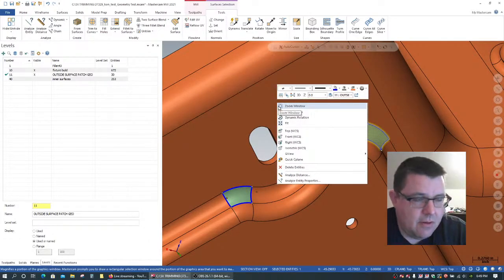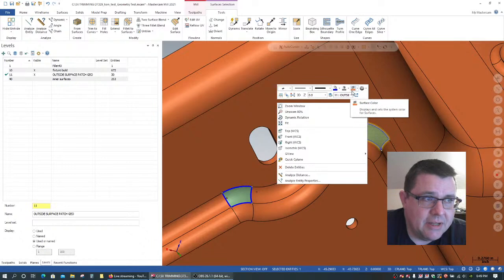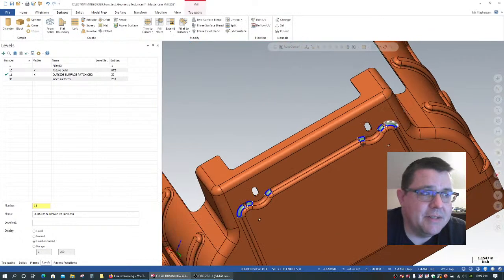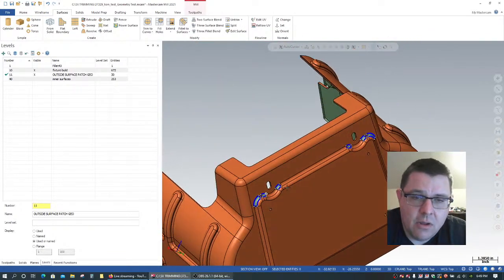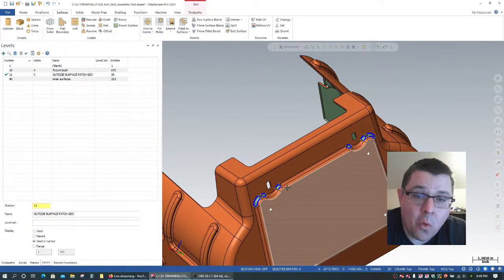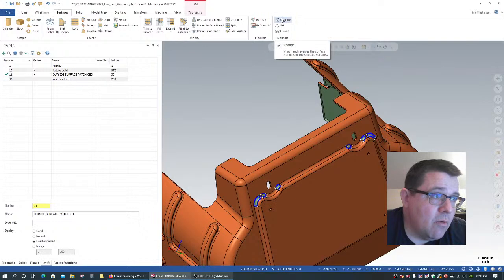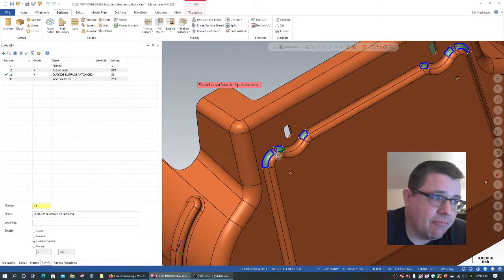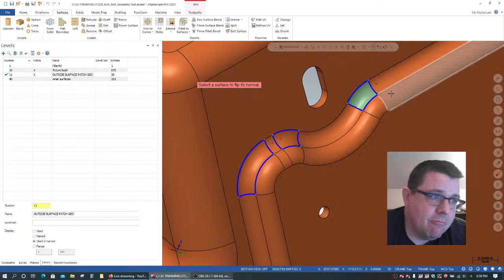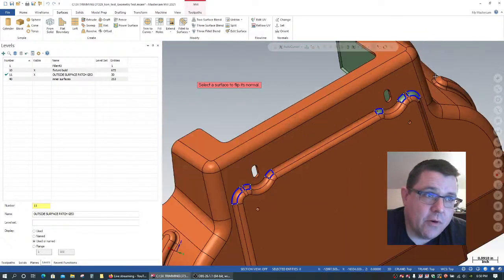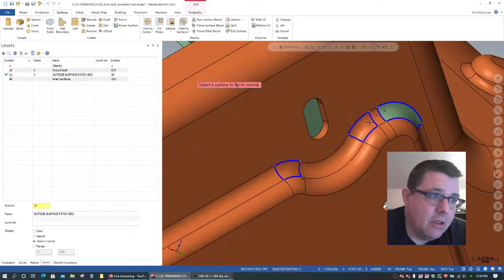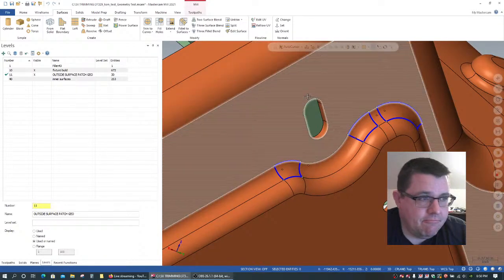and okay, so our surface creation color is orange, which means these surfaces are backwards. Their normal is reversed. So what we're going to do is go into the surfaces tab here, and I'm going to go over to the normals option and click on change, and I'm going to reverse those normals.